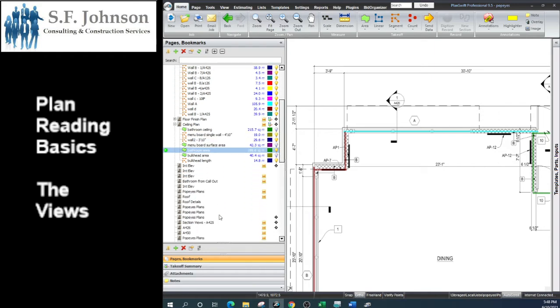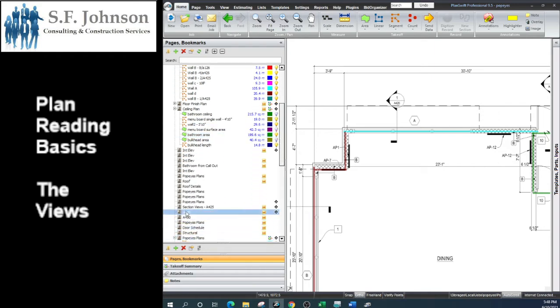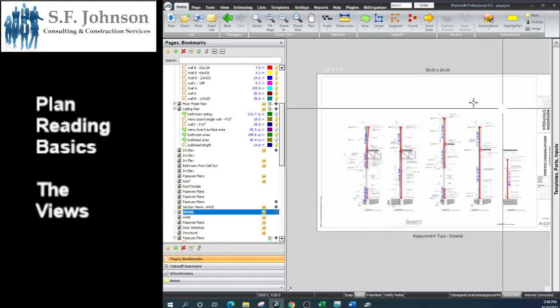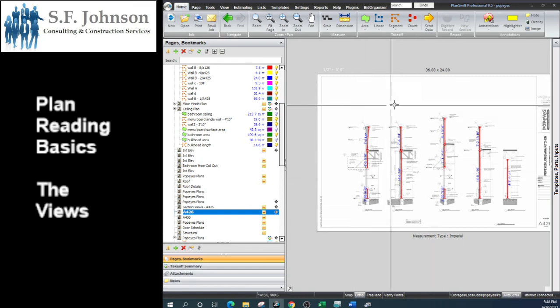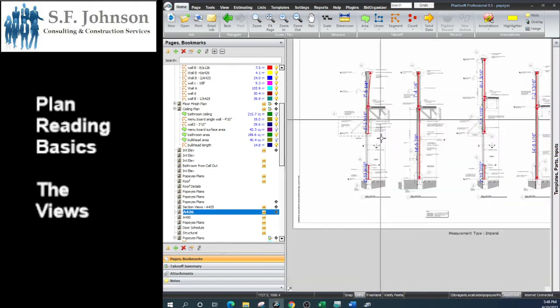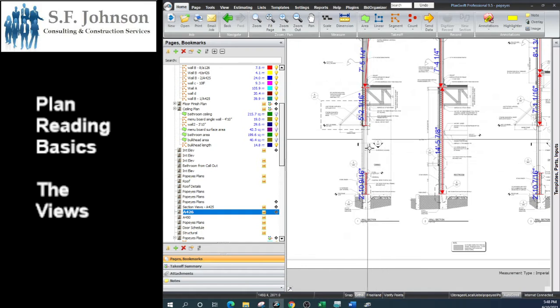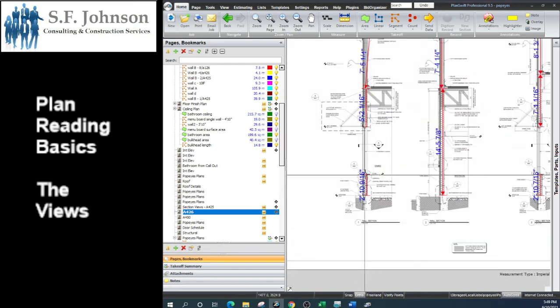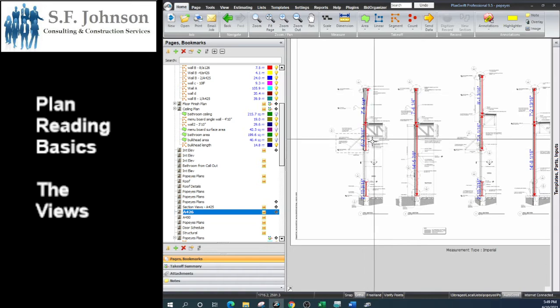Here we go, 1 over. So now we were up here, right? We were up here from the plan view looking down. Now we took that section view marker and we came down here. Now we know what the wall construction is at that section. That was the wall at the window. There's the window. We have a certain portion of wall below the window, and a certain portion of wall above the window. And so we use this to determine how many linear feet of this size and height of stud. We can use this to determine our material quantities now.